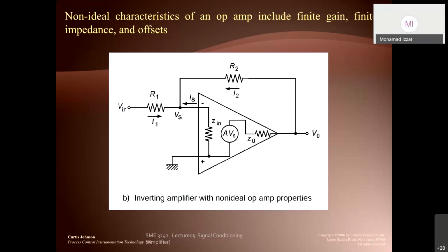So this is a very basic op-amp circuit, how you connect it. Outside you see R1 and also R2, those are typical, as I mentioned. You buy one chip, you need to buy two more resistors, R1 and R2, to construct the op-amp circuit. Inside, as you have seen in the previous slide, there is input impedance Z in and output impedance Z out, inside that triangle, inside the chip. So these must be there, otherwise it cannot work.